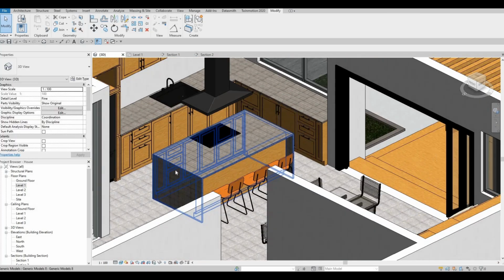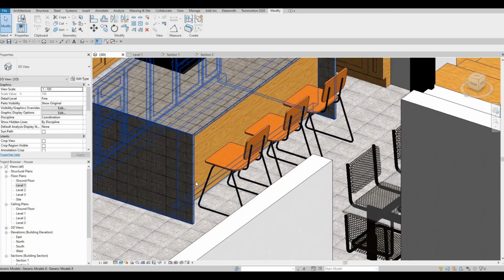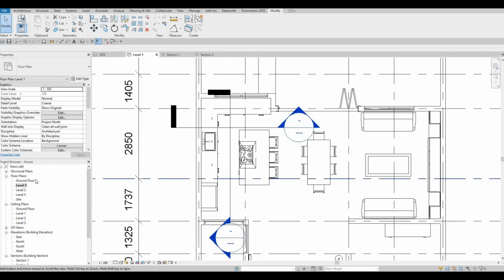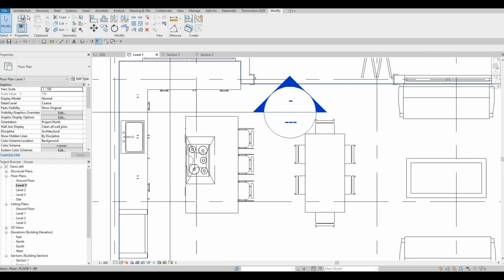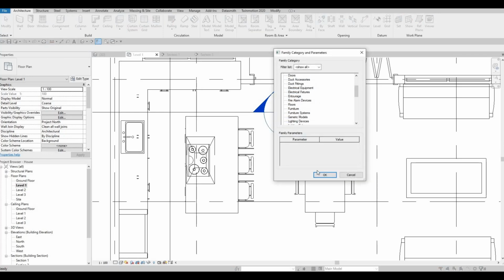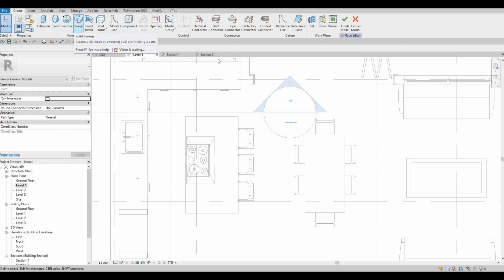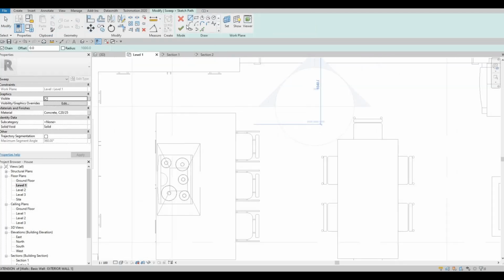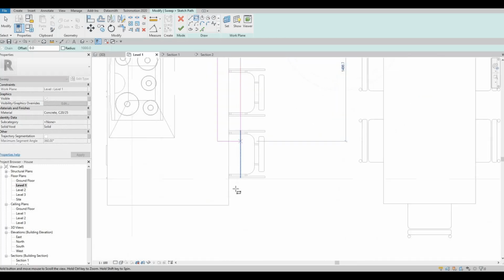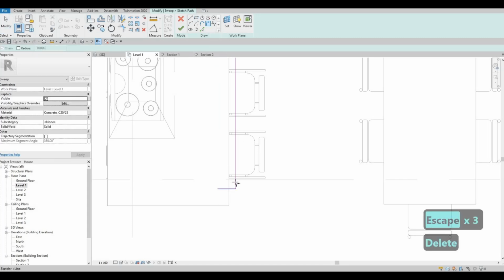and what I want to do next is to add maybe those knee rims here. So what I'm gonna do is I'm gonna go to level 1, and let's go model in place, generic model, and I'm gonna do a sweep, sketch path, and let's just maybe create this first, and then delete this, and then fillet arc here.